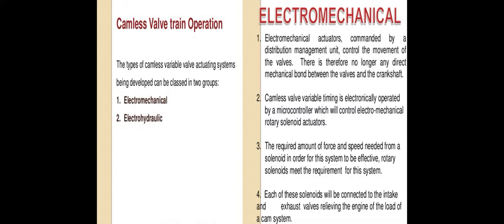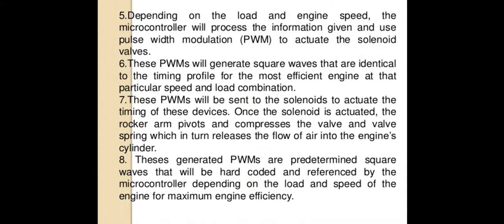Each of these solenoids will be connected to the intake and exhaust valves, relieving the engine of the load of a cam system. Depending on the load and engine speed, the microcontroller will process the information given and use pulse width modulation, that is PWM, to actuate the solenoid valves.